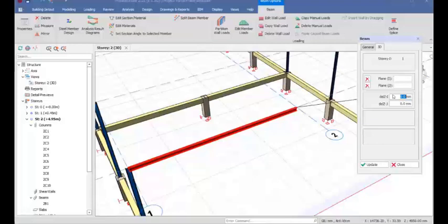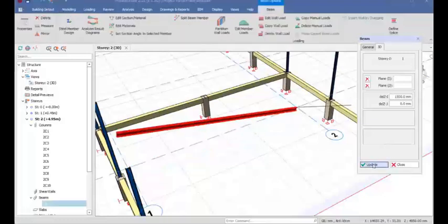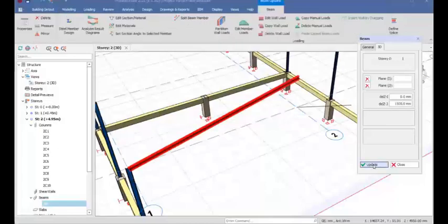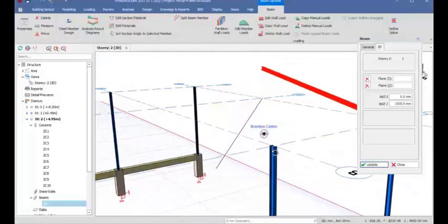We can take that to be maybe 1500. So click on the update right there. You see it's not in that direction, so you change directions, key in 0 right there and take it to these directions, and then key in 1500 as the apex height of the beam rafter. So we'll have something of this kind.